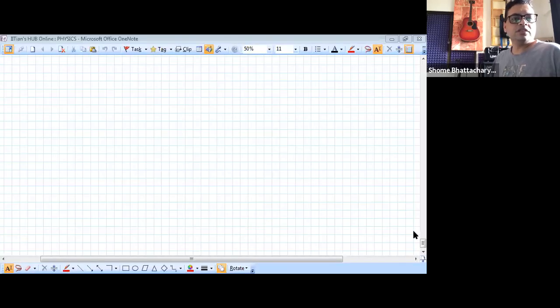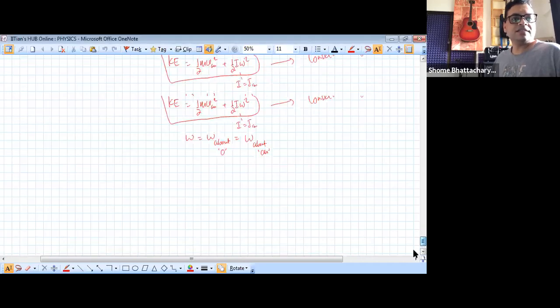So this type of problem is designed to be done by the instantaneous axis of rotation method. Whenever you see a situation like this, where you have this kind of constraint, that two points on the body, or any two arbitrary points, in this case the end points of the rod, are constrained to move in a certain way along a surface, you can find the instantaneous axis very easily.